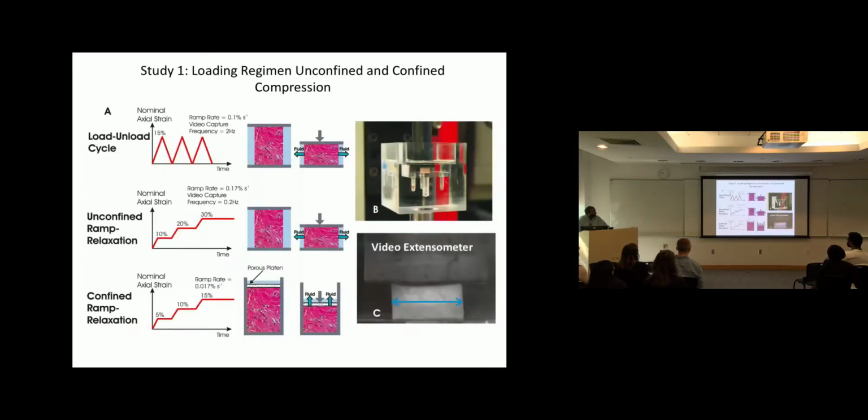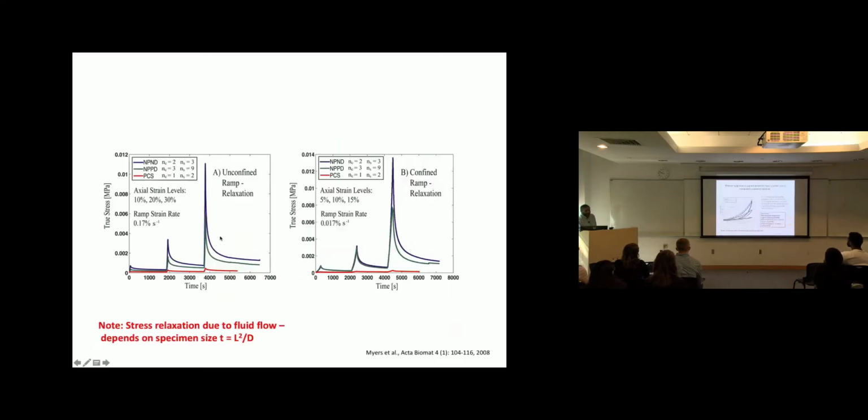Now let's look at this case. This meaning either one of these. Let's say the first one here. So here, if you plot the stress strain curve, what's happening is I'm ramping the load, so it's going there, and then I'm holding it there. When I'm holding the deformation there, if it's an elastic material, the force will stay where it is. But here you see stress relaxation. Here too you see stress relaxation.